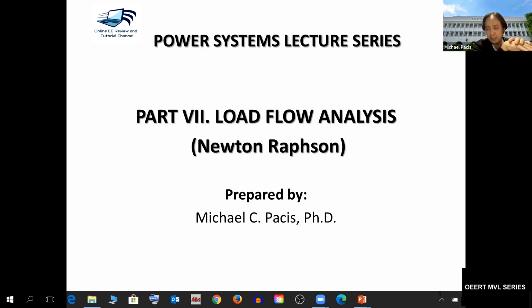And then from there, we used the algorithm of Gauss-Seidel, or the method of successive substitution, in order to get the load flows. But there's a limitation on that method, because if you have a very large system already, it will become ill-conditioned. When I say ill-conditioned, a parameter is changed on some part of the power system, and the rate of change is also very large. So you tweak a little bit of a parameter, and then the change becomes very large. Then it will become divergent.